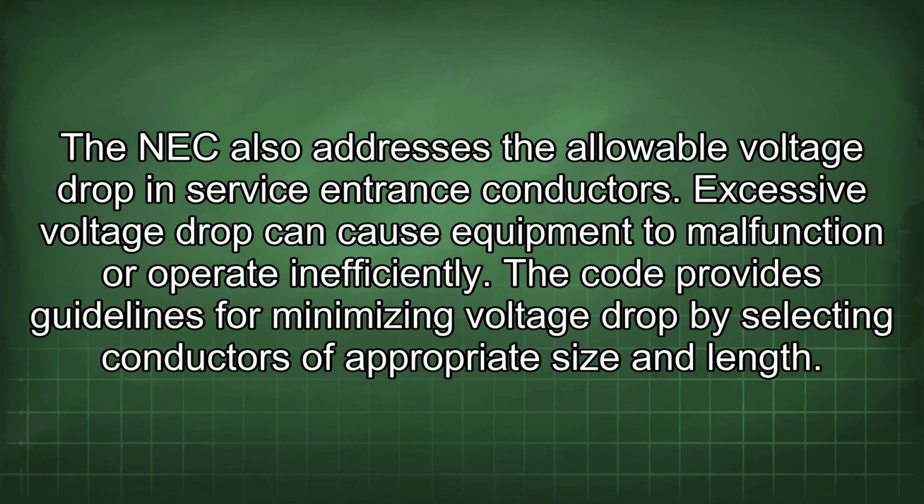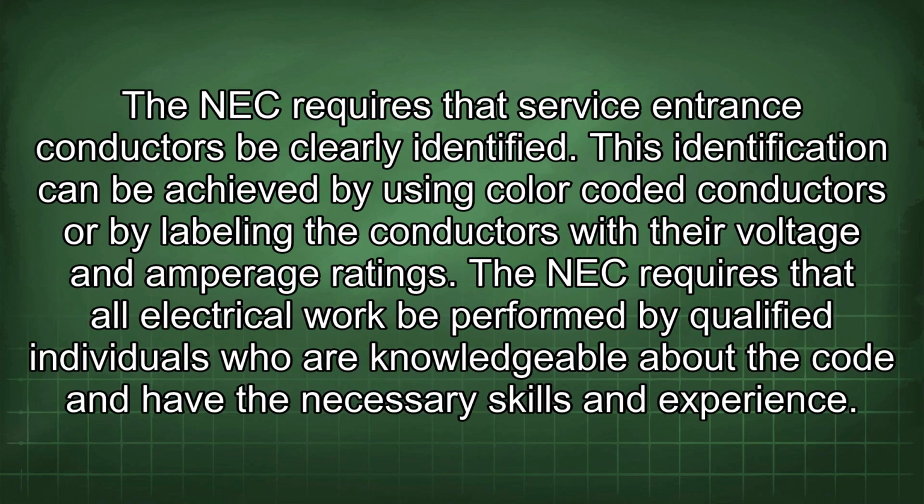The NEC also addresses the allowable voltage drop in service entrance conductors. Excessive voltage drop can cause equipment to malfunction or operate inefficiently. The code provides guidelines for minimizing voltage drop by selecting conductors of appropriate size and length. The NEC requires that service entrance conductors be clearly identified. This identification can be achieved by using color-coded conductors or by labeling the conductors with their voltage and amperage ratings.